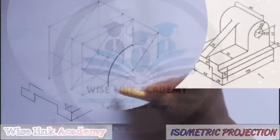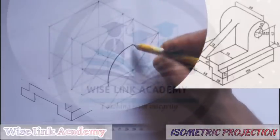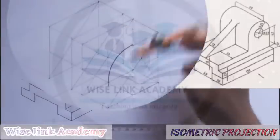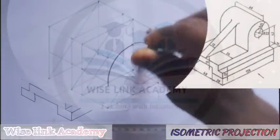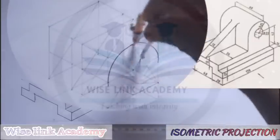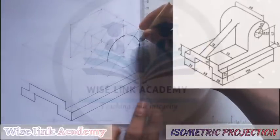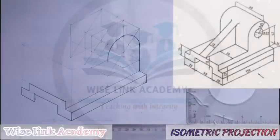So I have drawn this curve from this point. Extend your compass, draw this curve. Next task, take this point here to this, to this. So where this line cuts the diagonal is at this point. At that point, I'll take my compass and draw a complete circle. Right? I have this. So next task is that I can successfully take that line downward this way. So I have this. As you can see, we are progressing, not regressing.